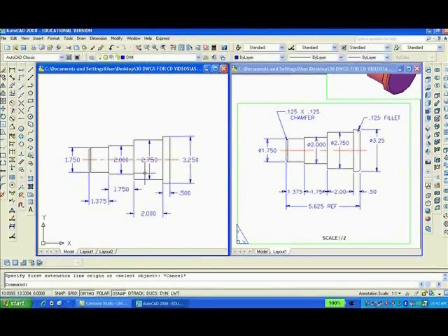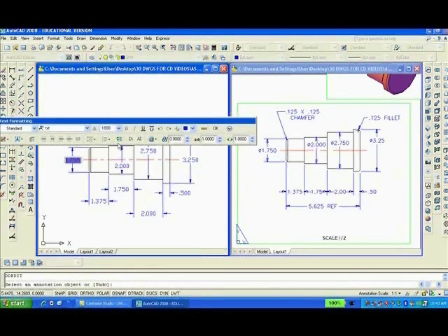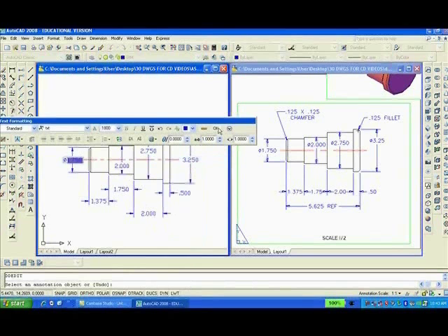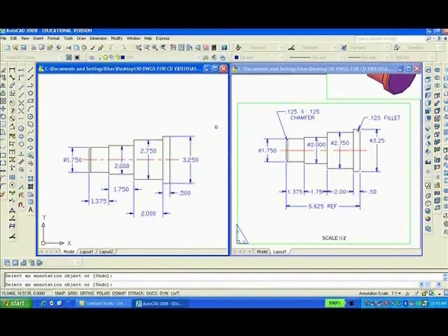Probably a good idea to get those dimensions away from the center line. So I'm taking off O-snap and ortho. I'm just going to click on the dimension. Maybe I can stagger them like that and do the same thing here. And just click on that and drag it down just so to get them away from the center line. So that looks okay. And if we want to, we can edit. ED enter. As you know, we can click on the symbol arrow and put a diameter symbol out front and click OK. Put a linear dimension, an overall dimension. O-snap has to be on.